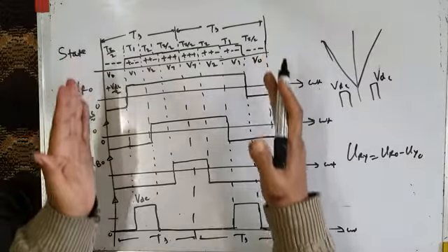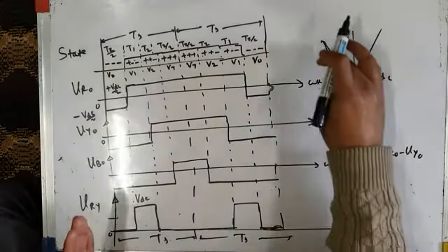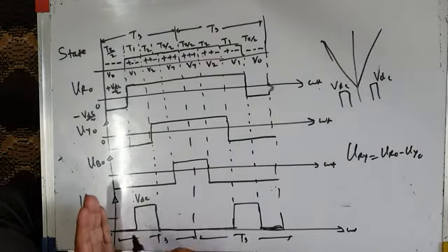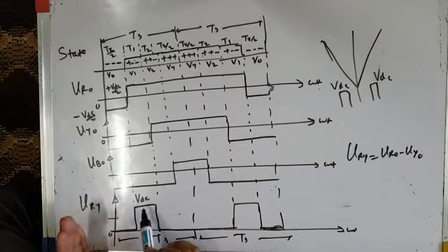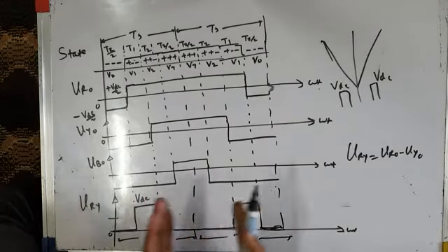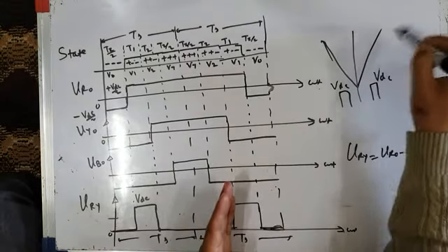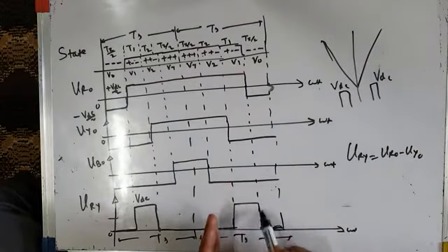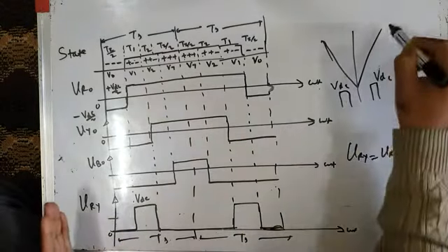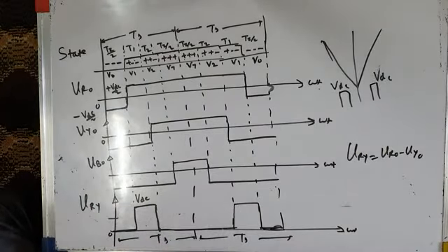In space vector terminology, we don't call it a carrier half period, we call it a sub cycle. In one sub cycle, one positive DC voltage pulse VDC will get applied across the load. In another sub cycle, which is equivalent to another half carrier period for triangle comparison, another voltage pulse VDC will get applied across the load. That means in one carrier period, or in 2 sub cycles here, 2 line voltage pulses get applied across the load.